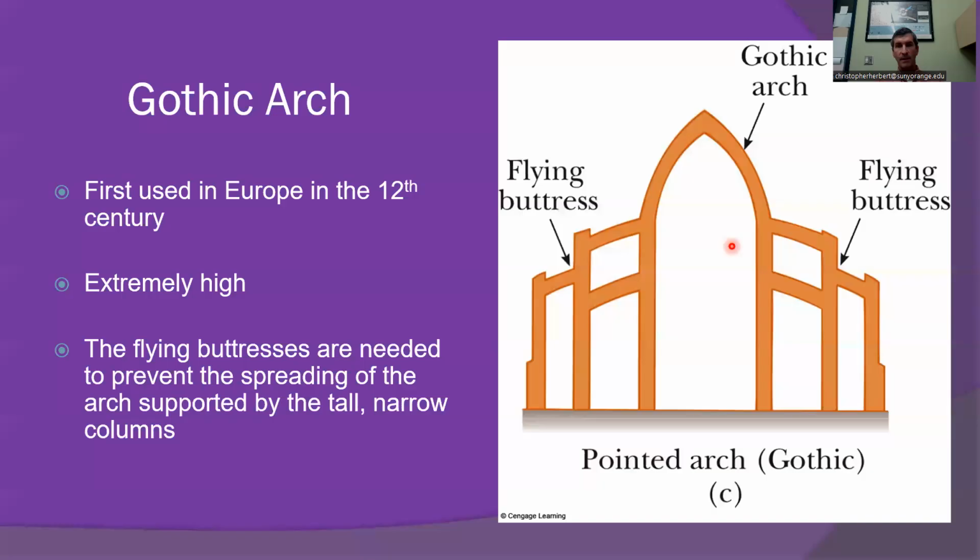So you had to create this flying buttress support to create an opposing force, because again, the Gothic arch just wants to separate itself apart, because instead of the forces going along this nice arch, they're actually directed this way. They're actually directed down this way. And what that will do is push the walls out.